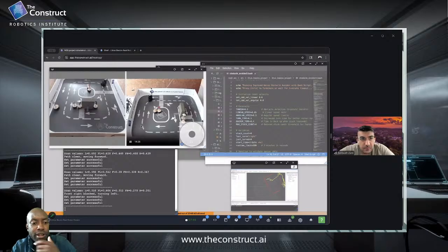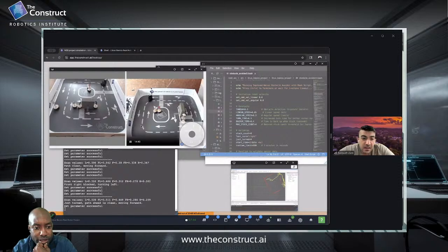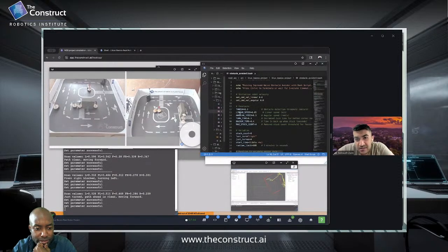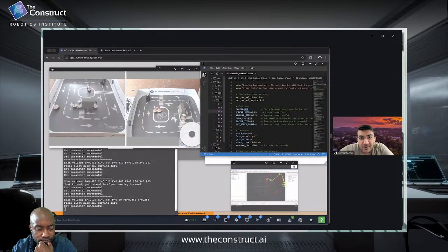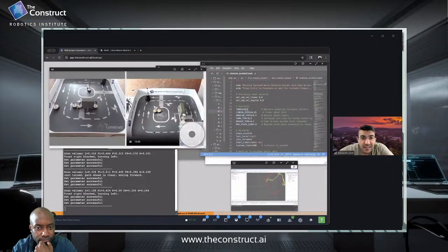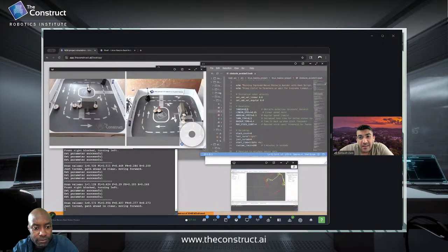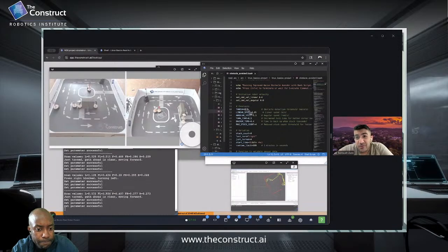So did you try the 0.1 value before you moved down to 0.05? Because I tried 0.1, maybe with the threshold of 0.1, and maybe that's one we don't have enough. Because I said, for example, here it's going to set the speed, and then it's kind of hit the wall, and then starts to measure all the other sensors again. I see. The threshold I think was too small for 0.1 linear speed.